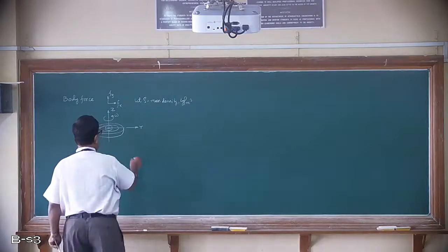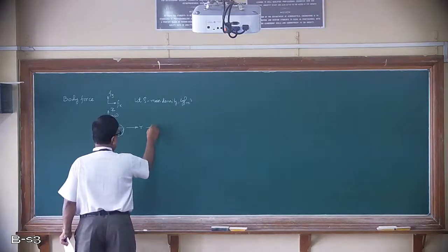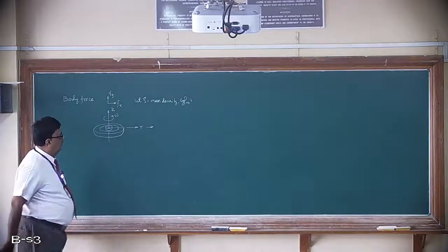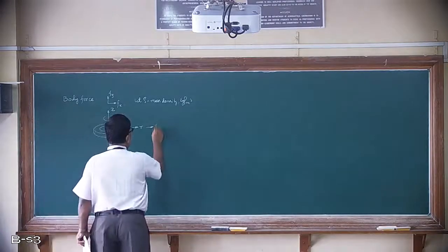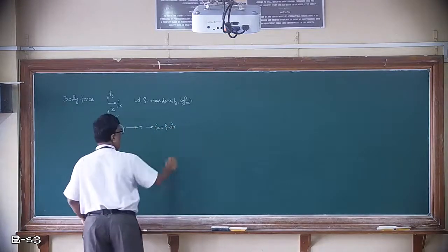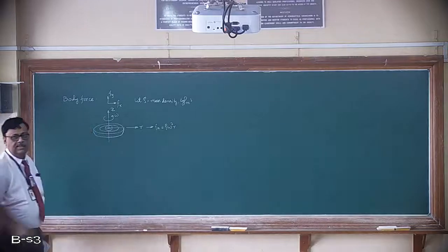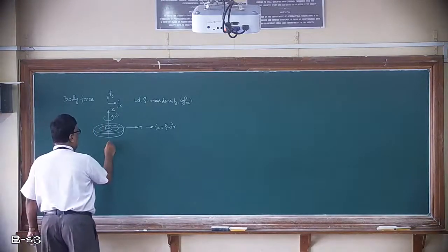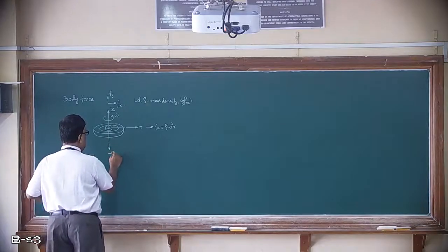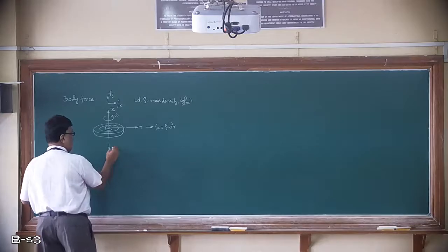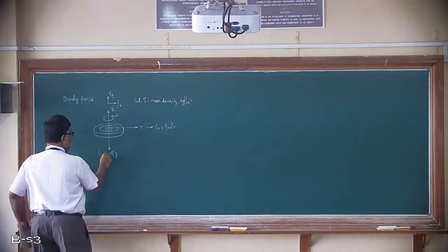Then obviously the centrifugal force, considered as a static condition only, with the Fx component being rho omega square r, is the centrifugal force acting in the r direction. Whereas the self weight, which acts in the negative direction, I can write as rho g. This is nothing but our Fy component.